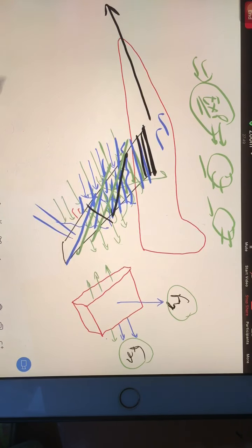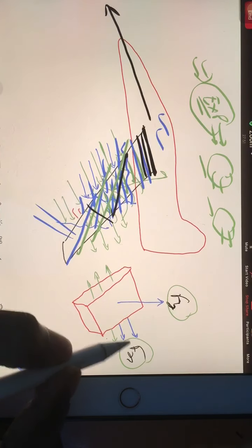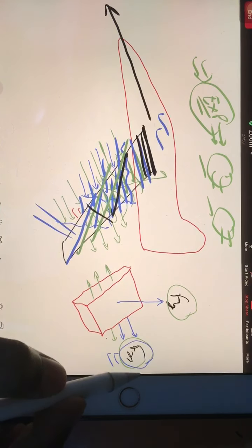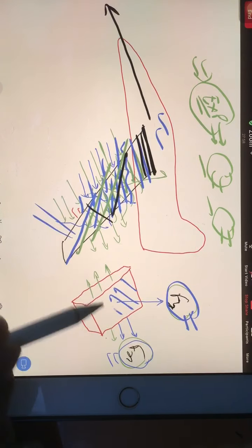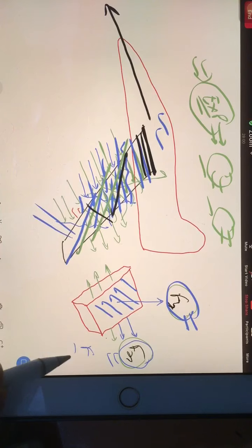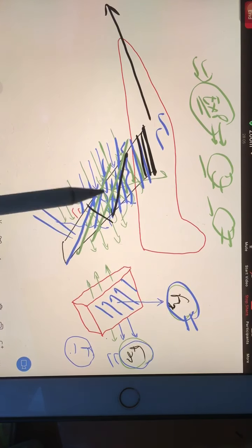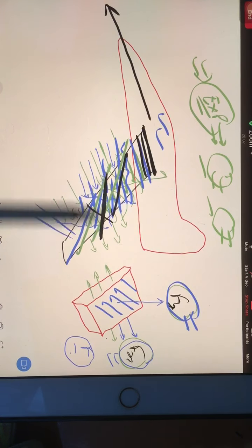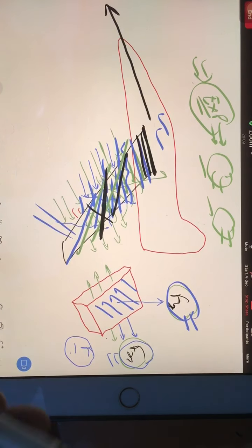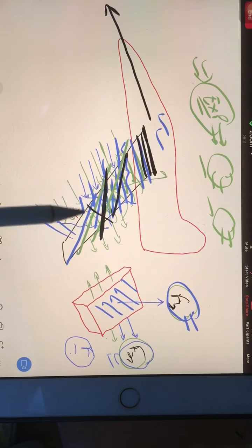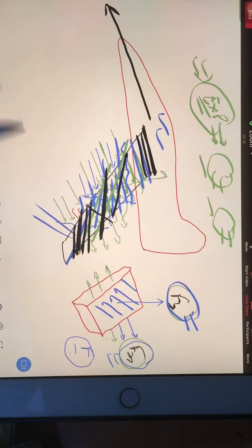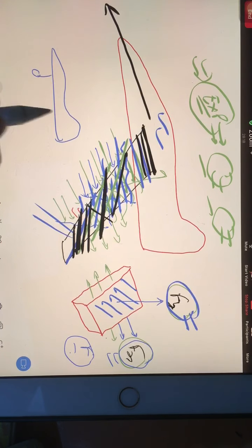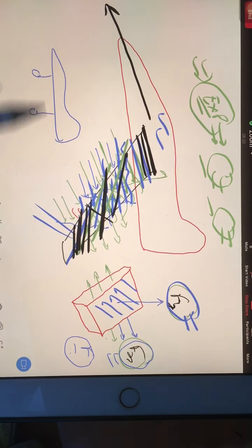So we have to know that for a given block, this is Fx. This Fx I can convert into stress, this Fy I can convert into stress, because I know clearly the area. So force by area will give me stress properly. But if I want to check whether my wing will break at this angle any time in the flight or not, whether my wing will break at this location any time in flight or not, it's like when the aeroplane is standing in the parking, that time no problem.